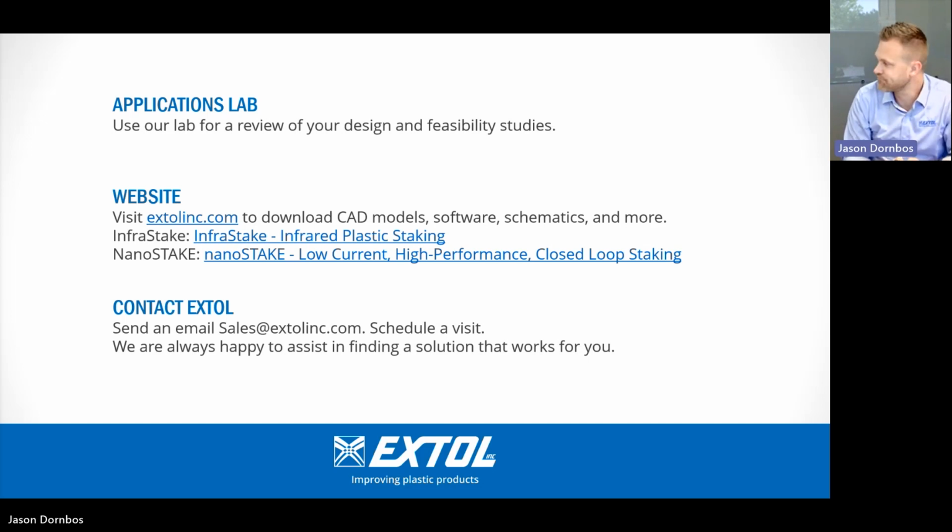Yep. And then there's the processing assistant for InfraStake as well, where you input your general boss dimensions, the color and the material, and it spits out some parameters for you. Then it runs you through the iterative process. You stake something, observe the process, answer a couple simple questions, and then it'll adjust the settings for you and dial things in. So that's with InfraStake.